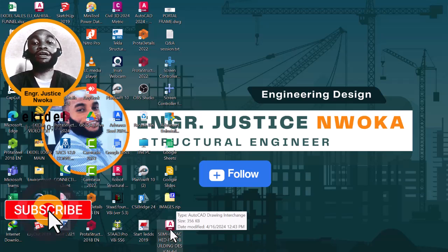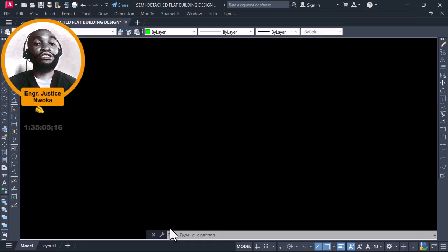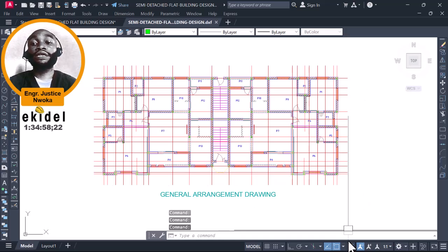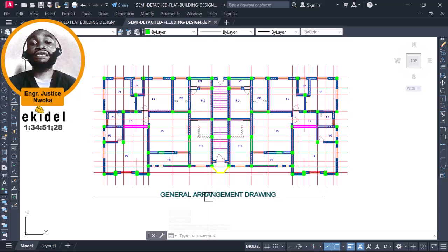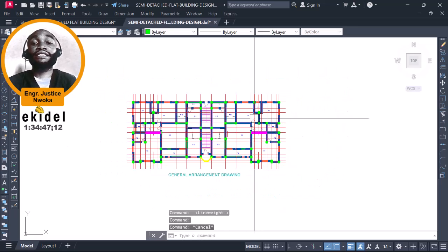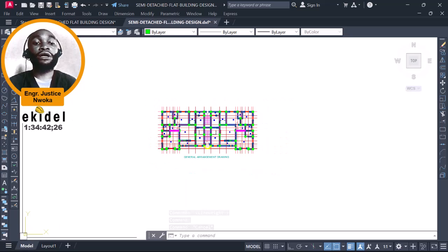So the next thing I'll do right now is open the file again to set the drawing at origin. Because when you are exporting a DSF file from AutoCAD to Protastructure, it's meant to be saved at origin. That's the best practice, to save your drawing at origin. So with this, I can quickly remove this text, or I can choose to leave it if I want. The next thing now is to save this drawing at origin, because you can see that our UCS coordinate is far away from our drawing, so it's meant to be with the drawing.